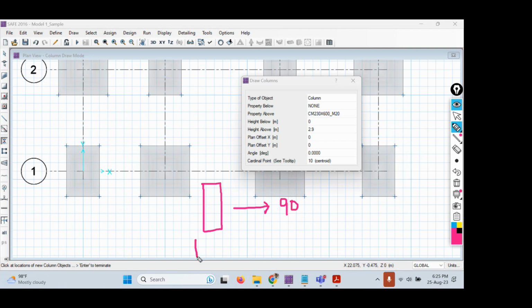If you want to orient along the x-axis, then the angle should be 0. Now, in some drawings we have typical orientations with some angle. This will have a 135 degrees or 45 degrees angle based upon the rotation factor. That's how you can orient the columns.